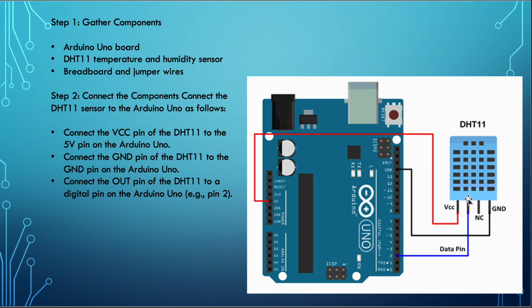We can go through the data sheet and we can see what is the power needed, right? We can directly give power from a 5-volt output. Where is the 5-volt output? We talked about it when talking about Arduino circuits, right? There is a separate 5-volt output on Arduino, so you can use that to give the power input for this. So that means, okay, 5 volts is given out. Do we need to connect a different power source to the Arduino circuit, or can we use the USB port to power this circuit? What do you think?